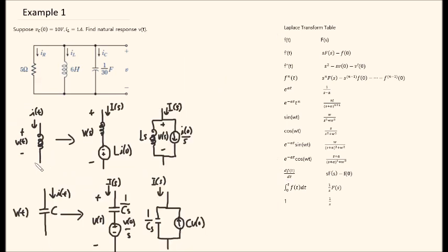So in summary, if you have an inductor, you can replace the inductor with one of these two circuits in the Laplace domain. And if you have a capacitor, you can change it to one of these two circuits according to our usage.